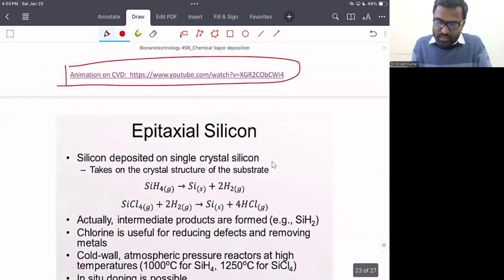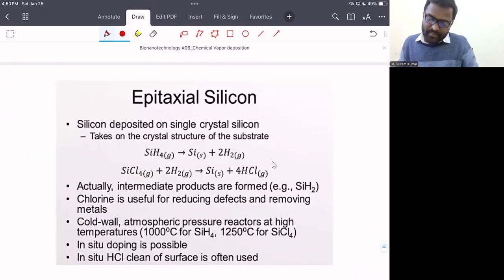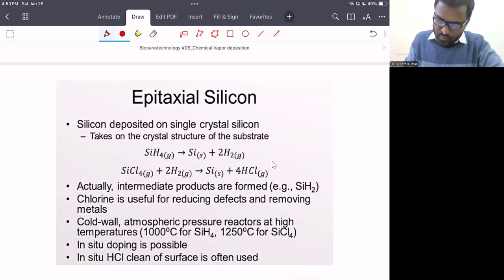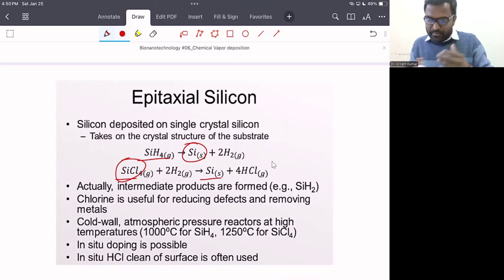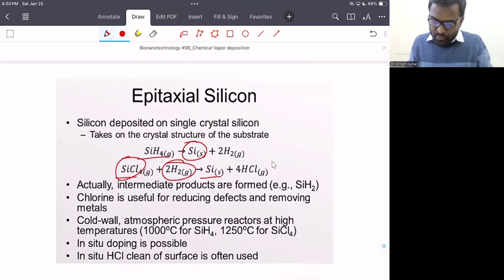And if you want to see some examples of how this CVD helps in the formation of thin film: if you want to deposit thin film, you can use silicon hydride, or maybe you can use silicon kind of materials, and based on that you have different temperature, pressure, or maybe different kind of additional gas, and based on that you will get the fine deposition of the silicon.